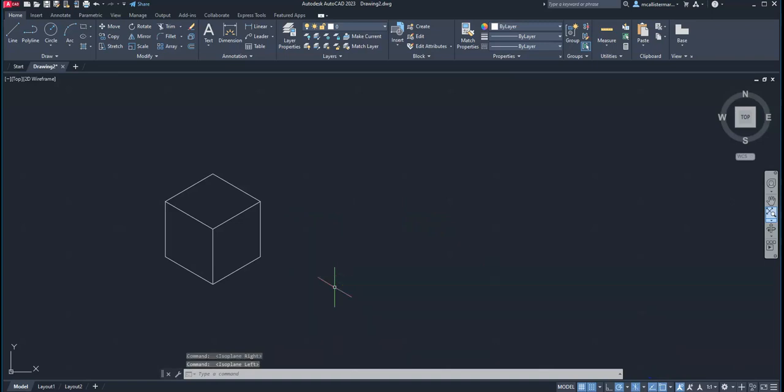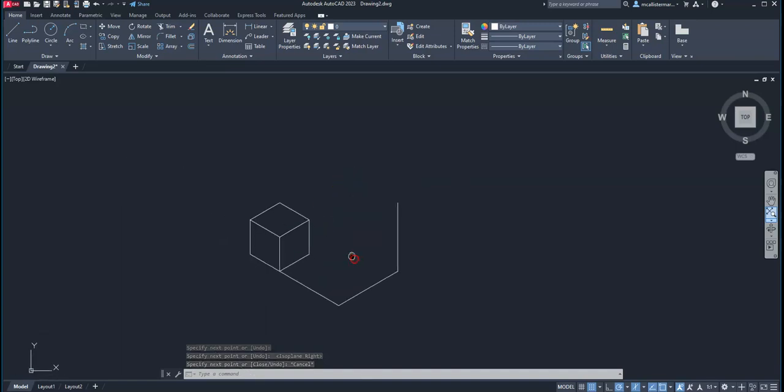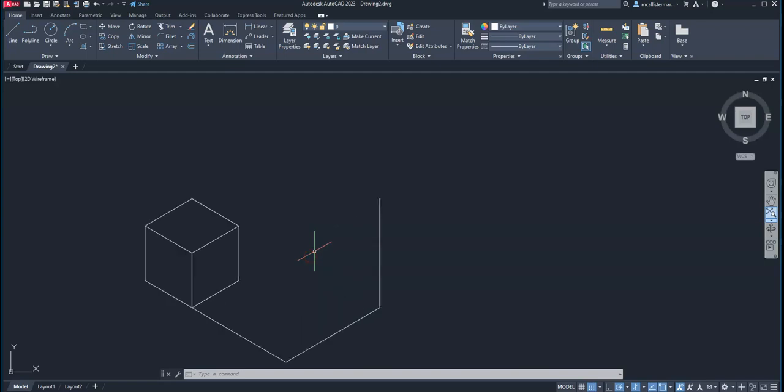But if I hold down Control and hit E, the cursor will change along with what I wanted to draw. So theoretically speaking, if we wanted to turn off our grid, and I wanted to sketch just off of this surface right here, and I want to hit escape and go ahead and hit Control E and change the line, I can change as if I'm on the top and come back, and we can go ahead and sketch an isometric sketch based upon how we have our cursor. That allows us to create a pretty simple isometric sketch, and also to change how our cursor sees.